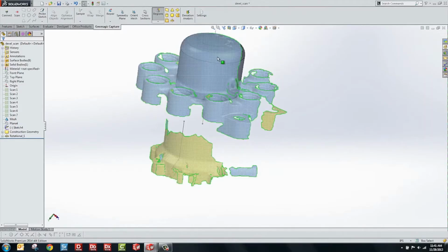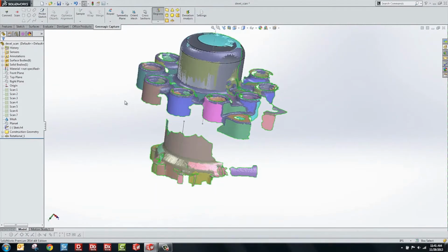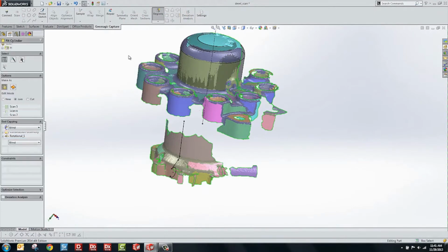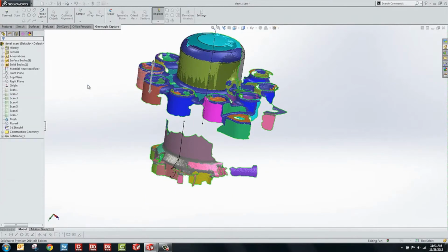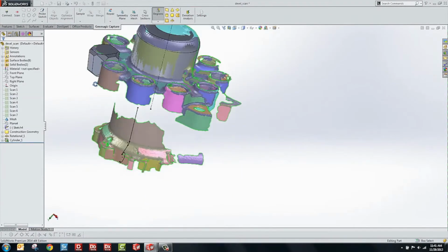Okay, we have the top section here, and then we can go ahead and repeat that process a few more times and select different geometry types that we'd like to create. So you can see it's very simple. We select a region and hit the checkbox, and we create a piece of geometry. What I'll do now is I'll hide the scan and I'll array the geometry around that main rotational axis. We're going to do that because that's a standard activity. Again, it's a CAD type tool that users are going to do over and over again to create the models.